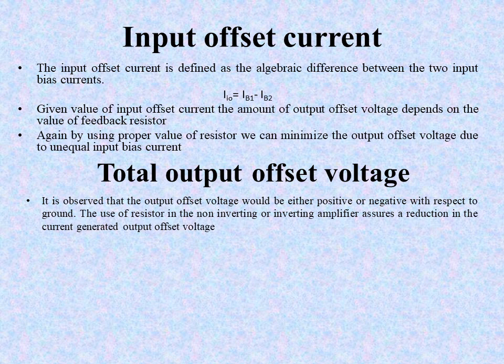So here, what we have studied up till now is that there are two things you should do before using an operational amplifier practically. First, the null pins should be connected with the potentiometer, and an additional resistor should be connected in the non-inverting end at least. This is the minimum that should be additionally added along with your circuit.